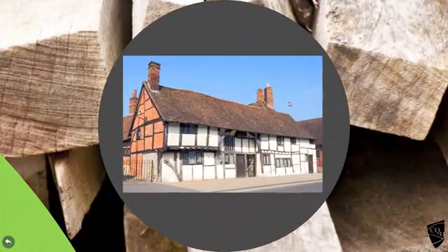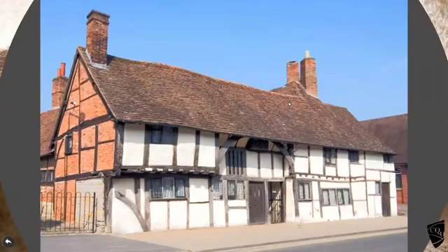Look at some photos. So there's a traditional timber frame property, obviously from England. These curved bits were from timbers that were curved in the first place. This is all oak. Notice I said it goes a silvery colour. You can see the framing on the side here. Interestingly, the brickwork is a later infill. This would have been known as wattle and daub, which we could look at later on for you if you wish to. And you can see this is an infill brick, but these are plastered, lime plaster, over a lattice of timber and reed, which is the wattle and daub.